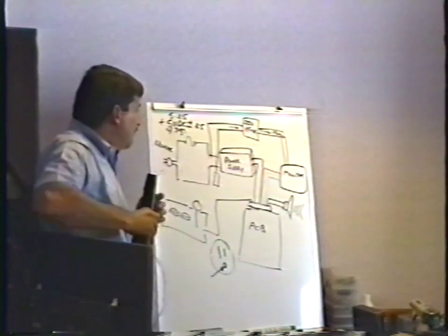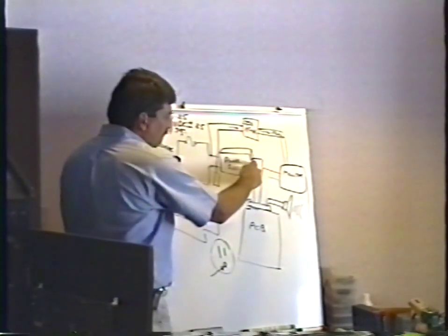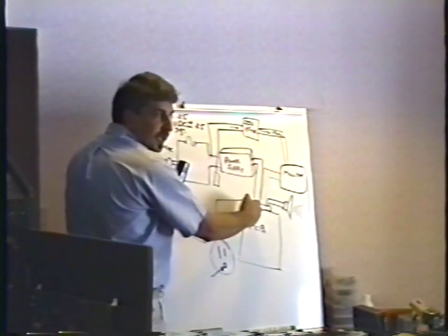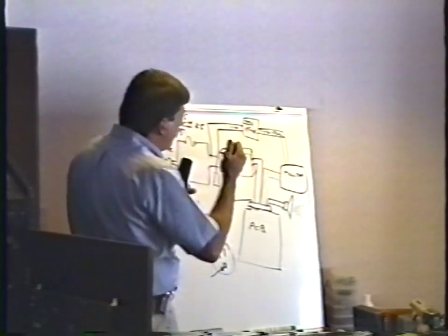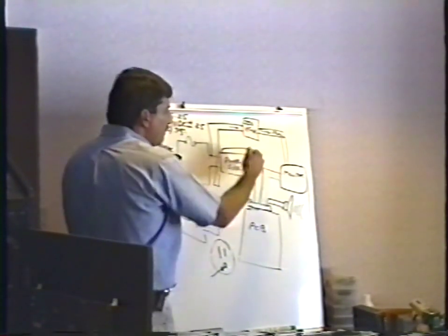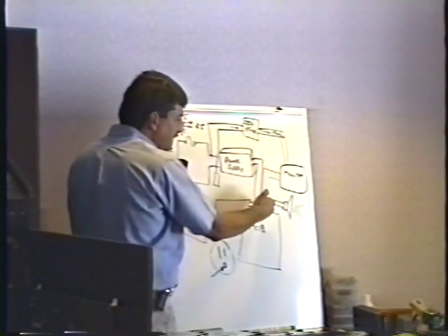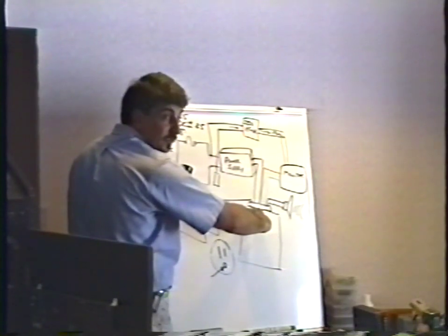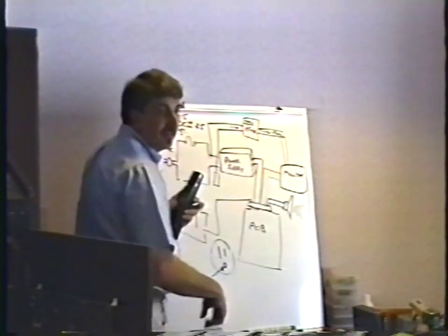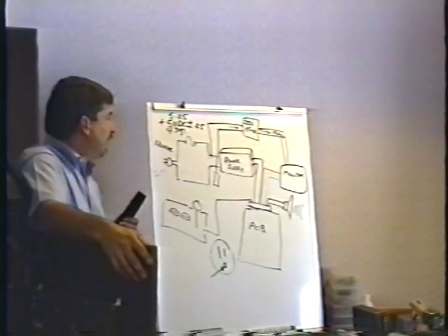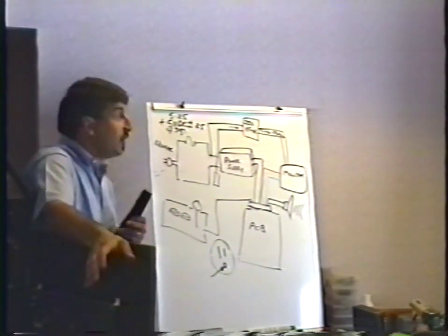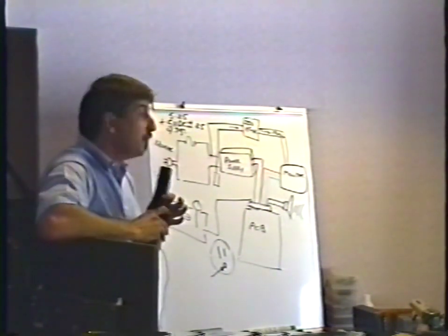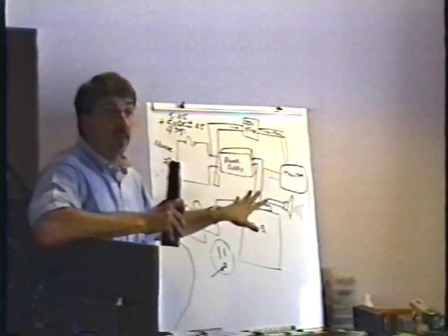You don't want to do that, because if you use this as a ground and just check the 5 volts here at the board, you're not checking this ground connection. In fact, I've screwed myself up that way. I've had a bad ground connection here. Using that as a ground, I checked it here, and I did have my 5 volts. But if I had gone right across from here to here, I would have seen that I didn't have my 5 volts. See, you're not checking that whole path that way. So when you're checking the power at the board, you really got to go right to the board. In fact, what I'm going to show you right now is an even better, more universal way to do this. Does this make sense so far, though?